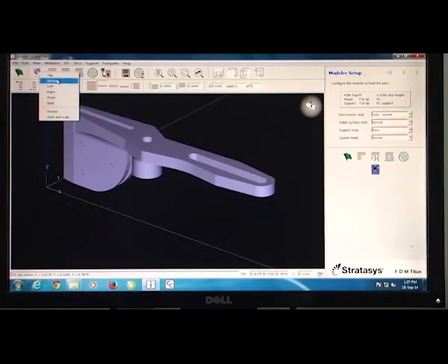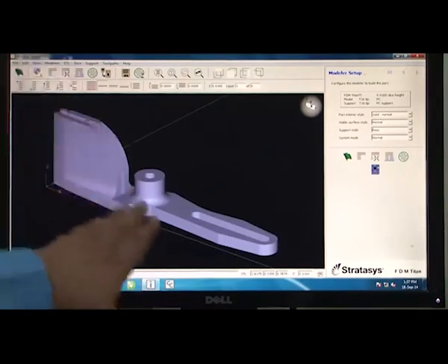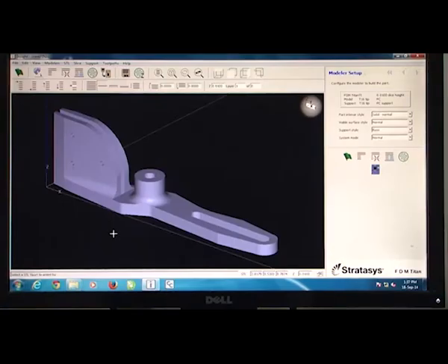Okay. So, I am going to actually now see what is the bottom. Okay. Take this up and then take this cursor all the way to this portion. So, this comes on the bottom and the part topples. Okay. So, now you can see the part has toppled and it has lied down on a flat surface, which is actually more appropriate for the purpose of doing RP or rapid prototyping.